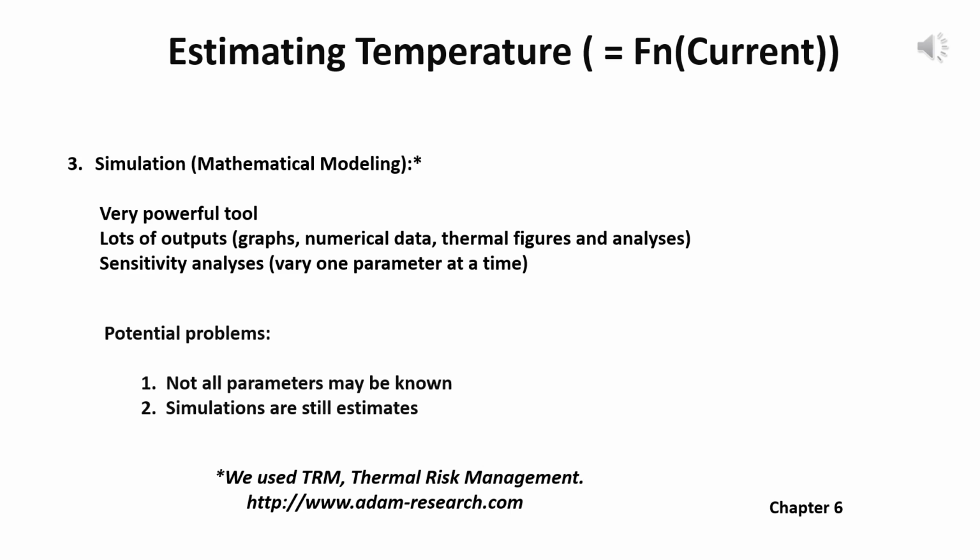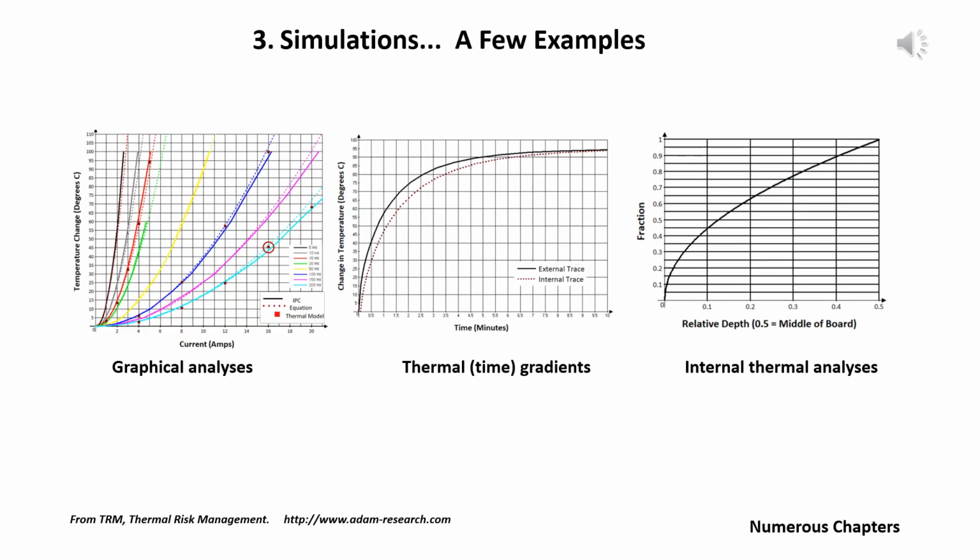But it's still not perfect. For example, not all the parameters may be known, and the simulations are still estimates. Nevertheless, on the following slides, I'm going to give you just a taste of some of the things we can do with simulation. On this slide and the next, I'll show you a variety of different outputs we can get from a simulation analysis. On the left-hand set of curves, we have a set of curves that look a lot like an IPC 2152 output, just drawn on different axes.